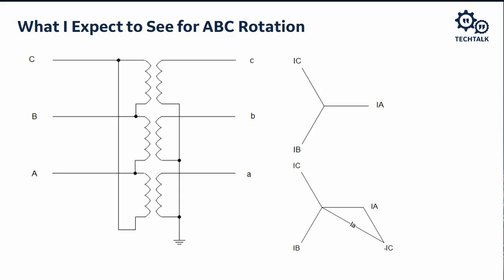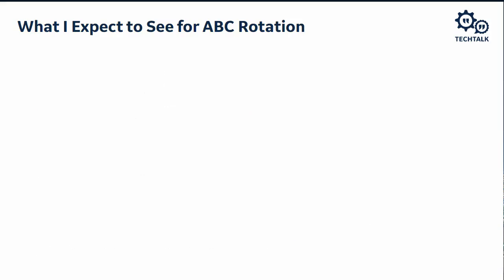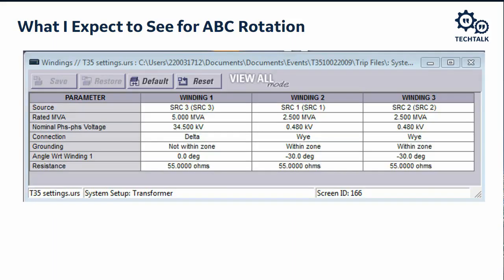And that's not really what I'm seeing there. What I'm seeing is minus 150. Now, that's okay, because of the way we actually wire the CTs. I expect it to be that minus 30 minus the minus 180. So what I expect to see is minus 210. It's really sitting at minus 150. If it were sitting at minus 210, the actual current, that would mean it's a 30-degree lagging transformer. And it's not. It's sitting at minus 150.